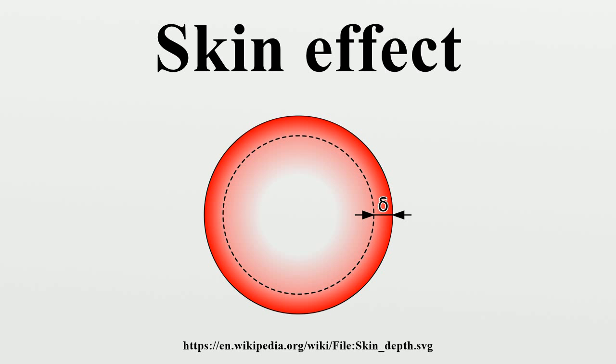In applications where high currents flow, solid conductors are usually replaced by tubes, completely eliminating the inner portion of the conductor where little current flows. This hardly affects the AC resistance, but considerably reduces the weight of the conductor. The high strength but low weight of tubes substantially increases span capability.